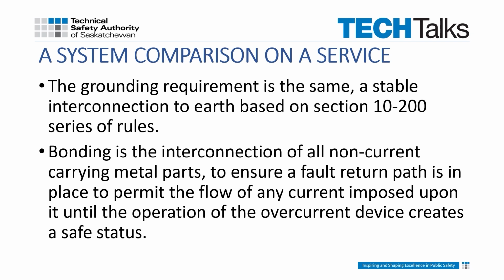A stable interconnection to earth is required as per the 10-200 rules in the CEC. In these same new systems, the bond is where there are differences, as the bond must allow a fault return path for available fault current until overcurrent devices operate to disconnect the current flow.